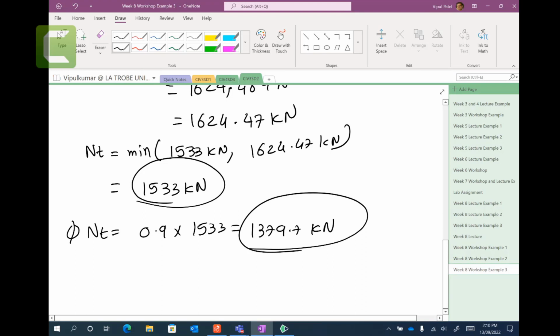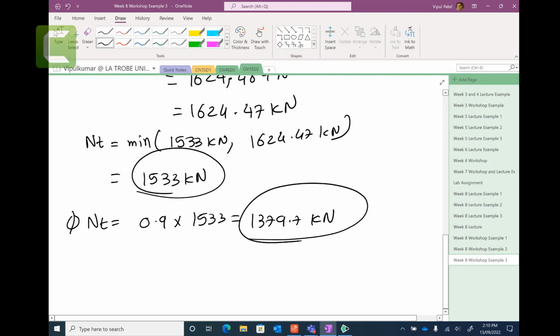Right. Someone might say, welding is good. Yeah, on paper, welding is good, but it's difficult for someone to go up there and do the welding. And we need licensed, good welders. It's not that you can send anyone and they do the welding. And generally, welds would be very critical and weak points in this because welds are brittle.